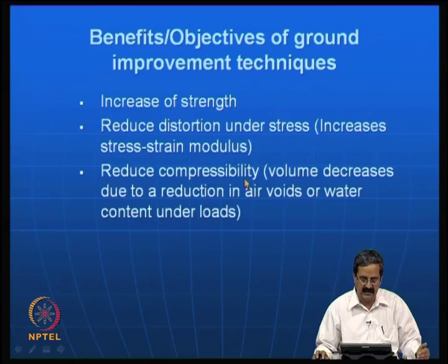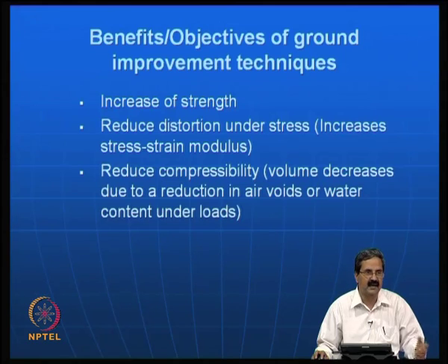Reduced compressibility is again about improved performance because of ground improvement, wherein the void ratio decreases. One can do preloading, or fill up the air voids with some materials, so that the compressibility is less and the material does not undergo a lot of compression.